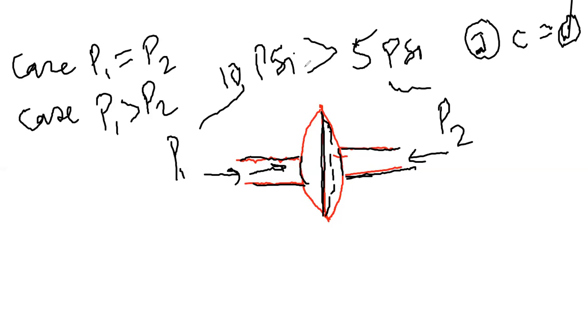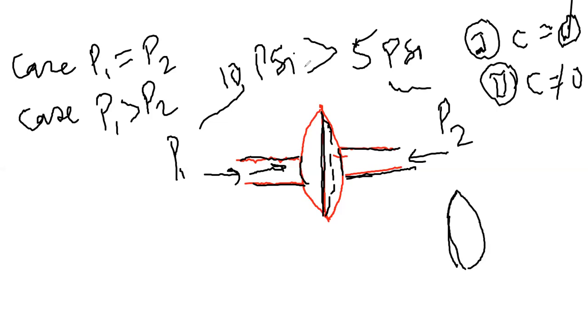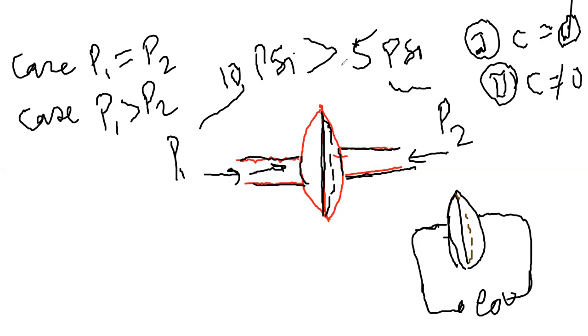So the resultant output will be generated for case 2. Here the output is not going to be equal to 0. This will lead to the movement of the plate. If the distance between the plates varies, at that moment we can measure the electrical output. So this is the change in capacitance, because I have got a change in the displacement of this plate. My distance has changed, and no doubt capacitance is a function of the distance.